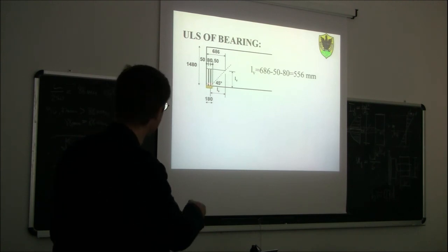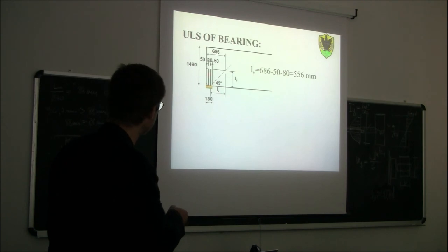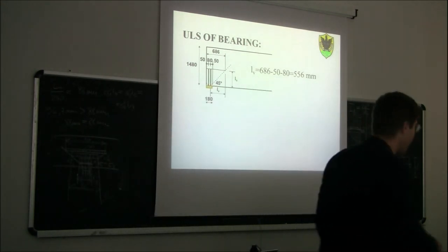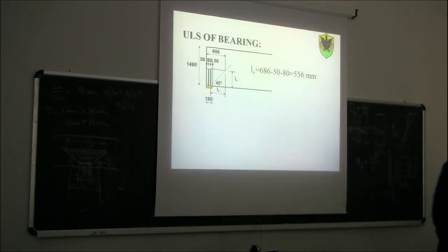You take these two lines, 45 degrees on one side and the other, starting from the screws. You see what is the minimum length of the screws needed in order for the point of the screw to reach this line, which has the minimum length required to make the verification satisfactory. So 686 millimeters. Okay? In this case, we're only calculating the minimum length of the screws.